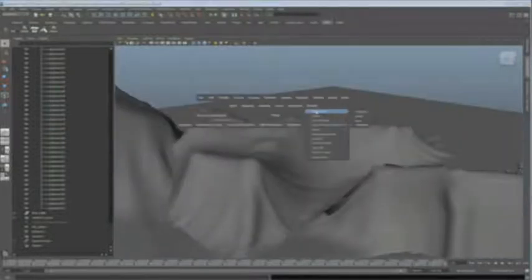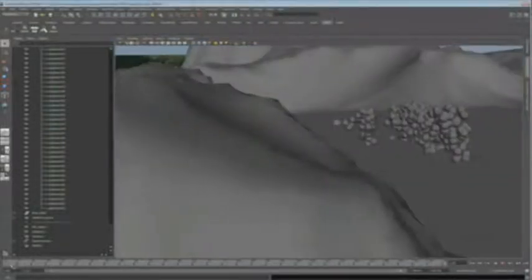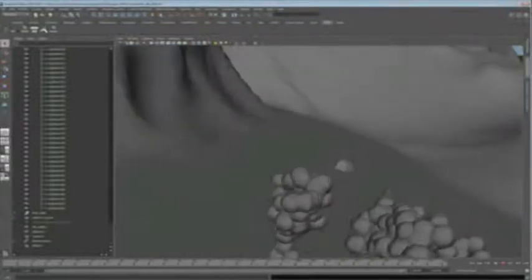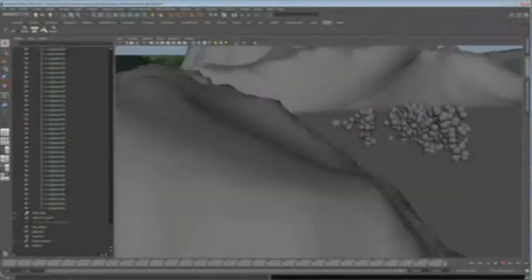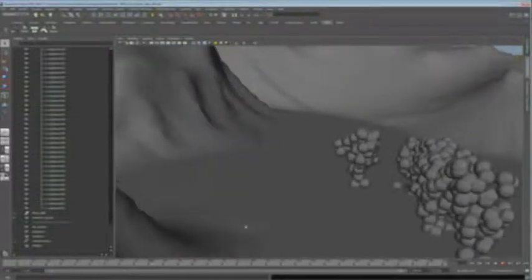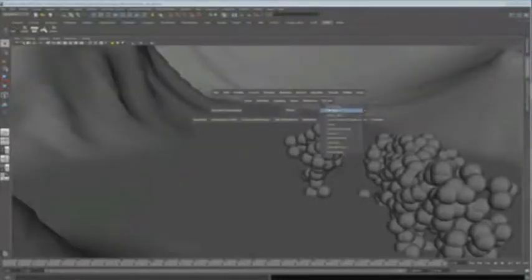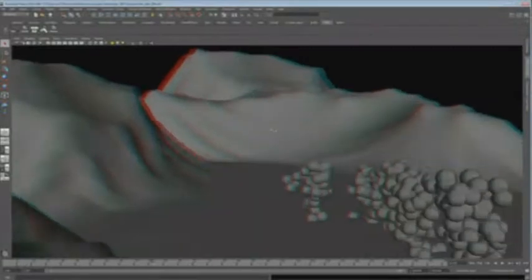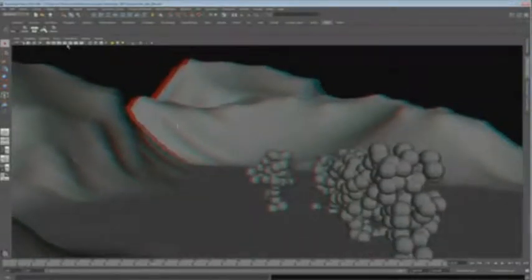So a little further along you can see the different cloths draped over the mountains and then a few spheres left in place for these trees. Rather than trying to get the individual leaves and branches of a tree here, what we're doing is roughing out the geometry, getting the correct depth, but leaving the job of fine roto and tracing the edges to the compositing tool. We're able to do anaglyph stereo viewing or other active stereo modes while we work.